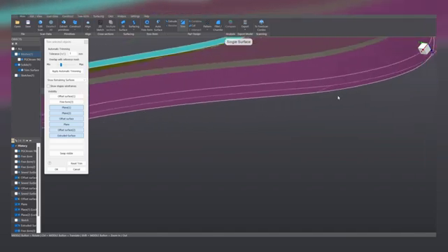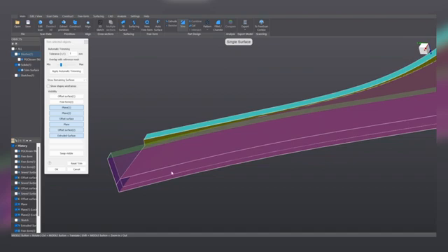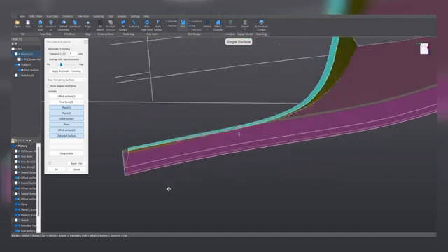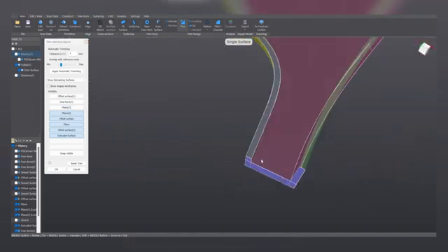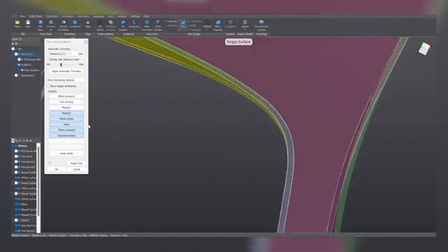Otherwise, the surfaces intersect with the volume of the solid, and eventually we are not going to obtain an empty shell, which is going to become a solid. Rather, we are going to obtain a surface, and this is something that we don't want. So this step is crucial and requires a lot of attention, and that's why we need to invest some time in checking this issue. So I've hidden this plane now.